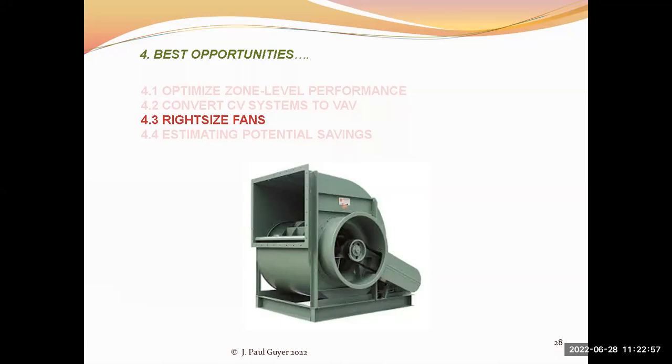The static pressure adjustment to VAV systems consists of reducing the static pressure on a VAV system for a reduction in the horsepower consumption. By gradually reducing the static pressure set point in the VAV system to a level low enough to keep occupants comfortable, fan speed will be reduced, thereby reducing energy consumption.